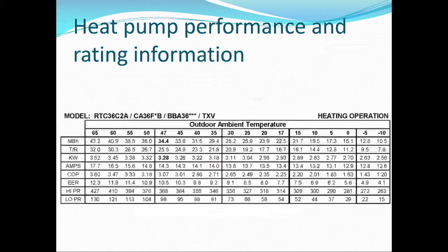This particular performance sheet or rating sheet is really useful for service, and this is really the only way that we're going to know how the system is going to perform and what efficiencies I can expect out of it. On the far left side, this manufacturer is showing what looks like about a 3-ton heat pump with a 3-ton air handler and a TXV, and it's giving me the capacities in MBH.